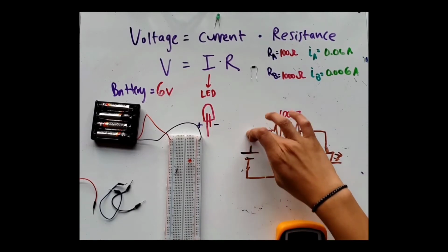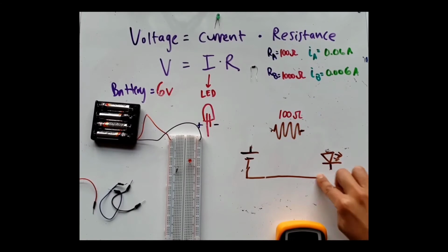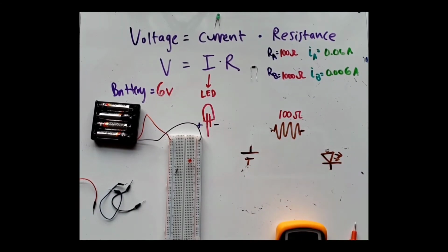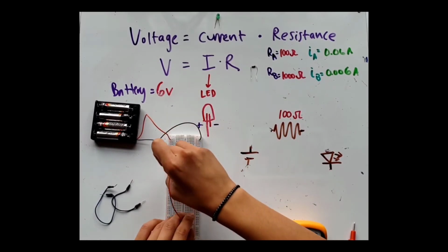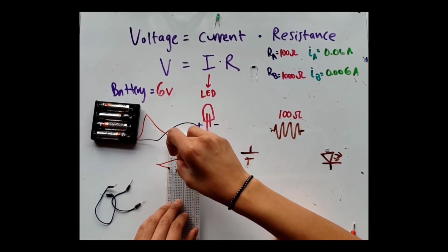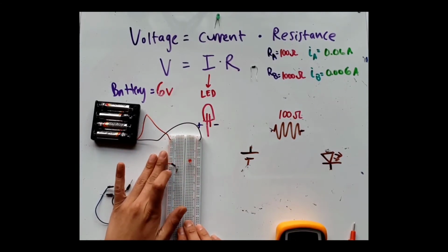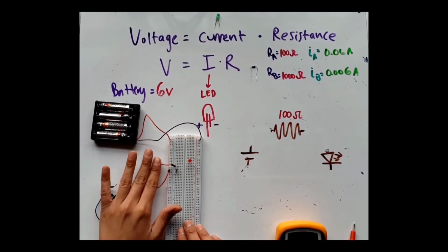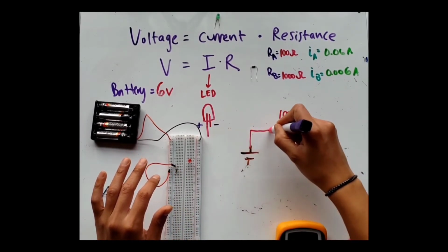Now if I look at my diagram, I'm seeing a floating battery, a floating resistor, a floating LED. So why is a breadboard important? Because it helps us connect all these components easier using just a wire. I'm going to get this red wire, connect it to the power rail, so anywhere on that column, and connect it to the top, which is 20A or 20C, D or E. All of those will work, but I'm going to use 20A because that helps me see my circuit a little better. So that wire is going from the battery into the resistor.